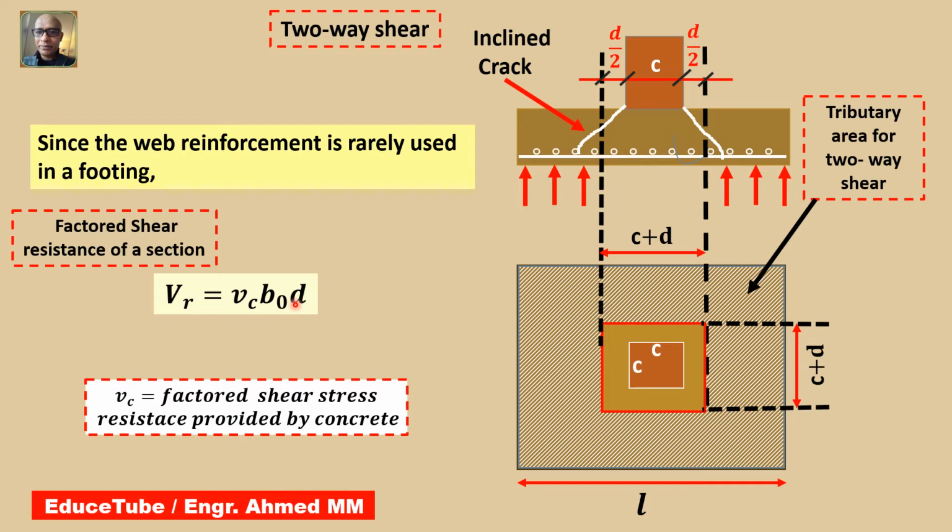So this VC, factored shear stress. It's a very important point. We have to calculate that, but we will use three equations. Out of those three equations, whichever gives us the least value, we will use that one to find this VR.